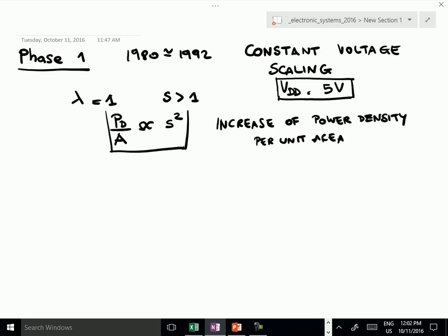Okay, of course you lose something when you decrease the supply voltage, because you can increase the clock frequency at a much slower pace, and in addition to that you lose back compatibility of the new integrated circuits with the circuits that you had before. Okay, but it's the only way to continue, because otherwise the total power consumption is not sustainable.